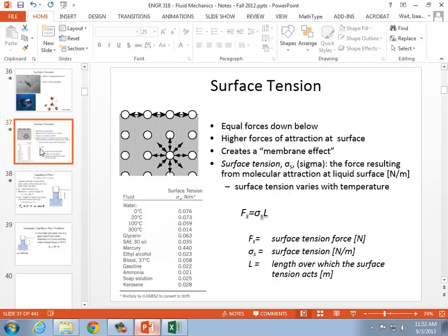The wetting angle for mercury, I don't remember offhand what it is, but the interesting thing about mercury is that if you put a glass tube down into mercury, rather than trying to maximize contact with the glass tube, it would actually try and minimize contact with the glass tube. There's more of a repulsive force. So if this is mercury, and you put in a glass tube like this, then it would be down here, but instead of having a contact angle of 0, it would be looking like this, really. And so the surface tension is forcing the mercury downward into the tube. All right.